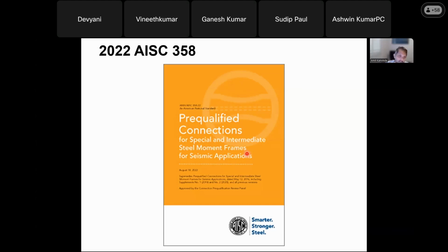these connections ductile. It's tremendously interesting, not only because it shows that little things in these connection details can create a huge difference in how those connections behave, but it's also very easy to use. It's very prescriptive. If you just follow the process here, you end up with a connection that is ductile, which allows you to use an R factor of 8 in some of these frames. Okay, so that was about SMRFs.